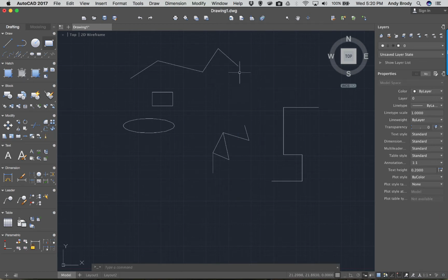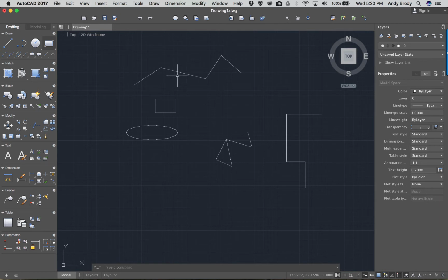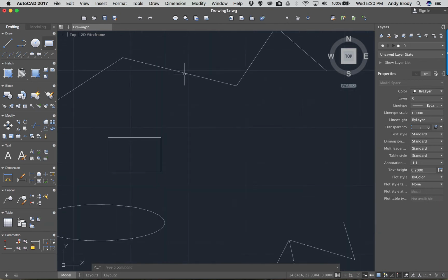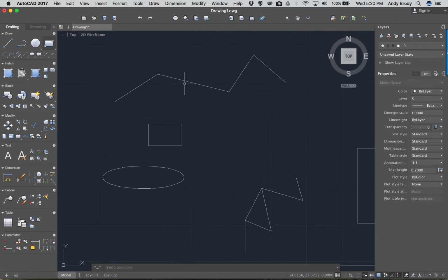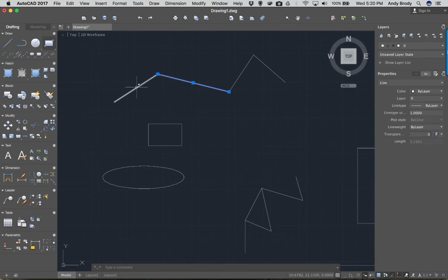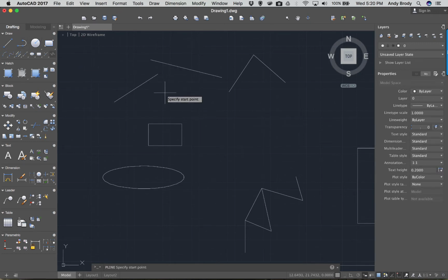I just hit the escape button. Again, you can't see me doing that. But having your finger near that escape button is very common in AutoCAD because that's how you stop your drawing commands without actually clicking another command. Anyway, each of these lines is unique and separate. They're not connected, so you can draw multiple ones. So try drawing a line. Try drawing a polyline. Again, just zigzag.